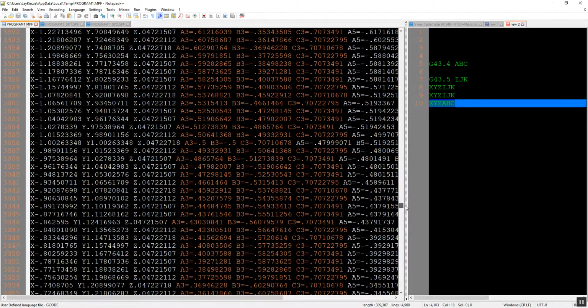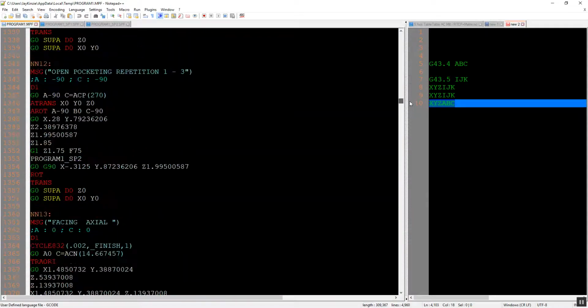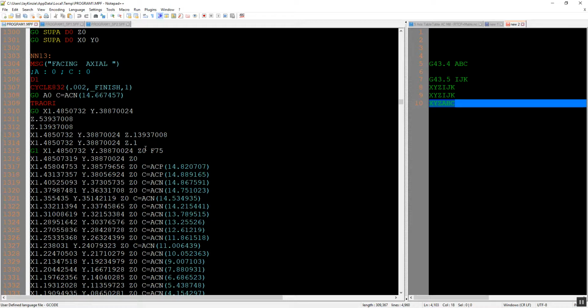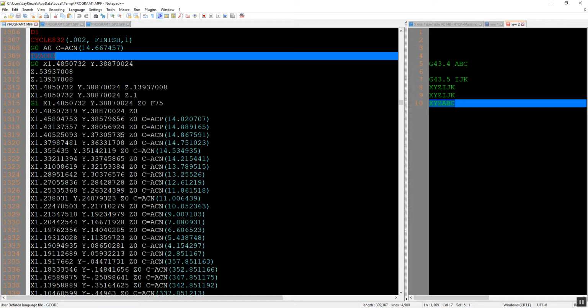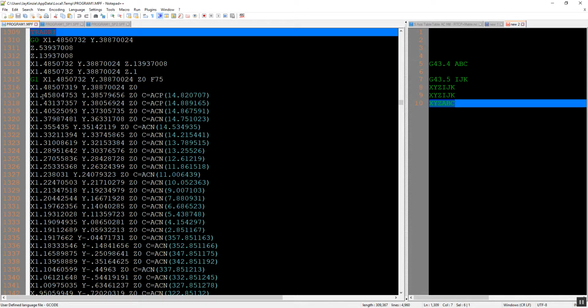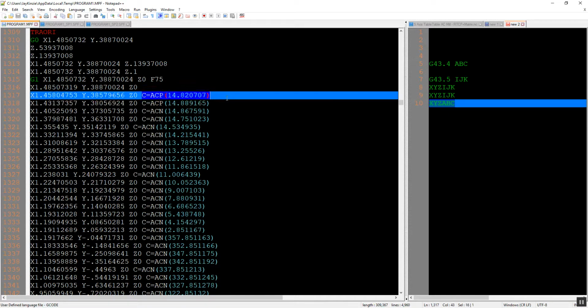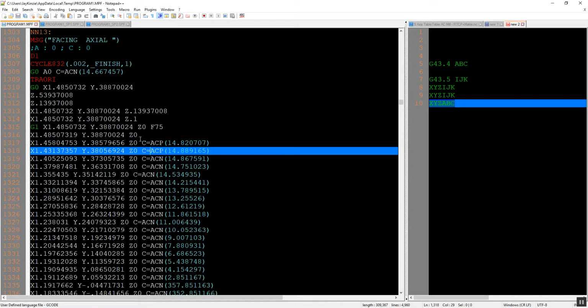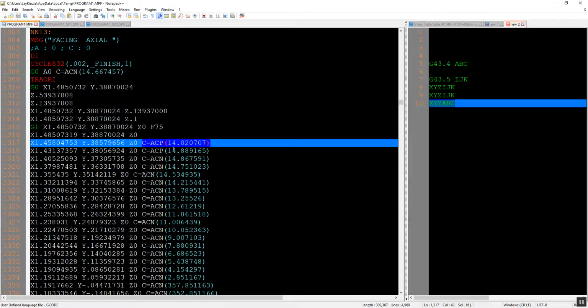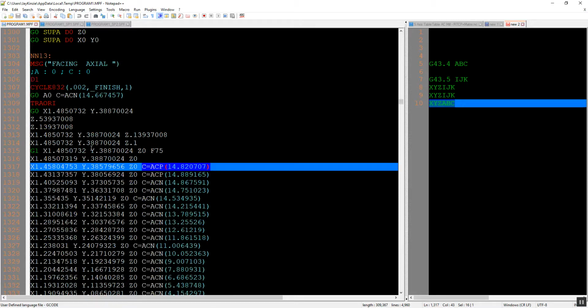But if we go back to that 4-axis axial path that we had, we're still cutting in with 5-axis Traori, RTCP, but we're outputting the C-axis here instead of the vector command, because if we were to output vectors here, the C-axis would not move, and we have explicitly asked the C-axis to move. So this post checks all that and makes sure that that's the case.